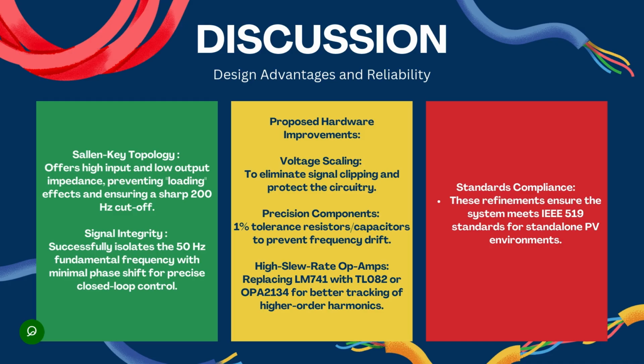Based on high slew rate op-amps, we can replace the LM741 with TL082 or OPA2134 for better tracking of higher order harmonics. Lastly, our design ensures the system meets the IEEE standard compliance for standalone PV environments.